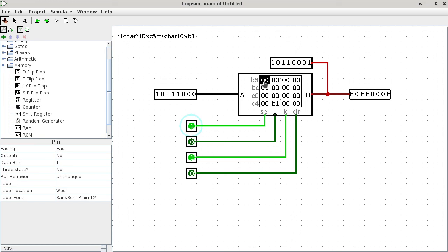But why is it called a bus fight? Because the data node is called a bus. A bus is basically multiple wires on the circuit board that serve one single function. So we actually have 8 individual wires with this node here. Now we see it only has one wire because it is easier to draw it that way, but on the circuit board, they correspond to 8 traces. But the 8 traces are really just different bits of the same thing, so we just call that a bus. That's a technical term when you lay out circuit boards. So this is called a bus fight, and that's not good.